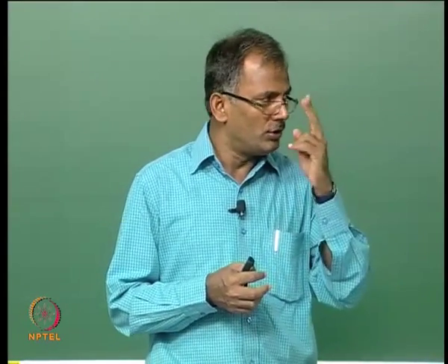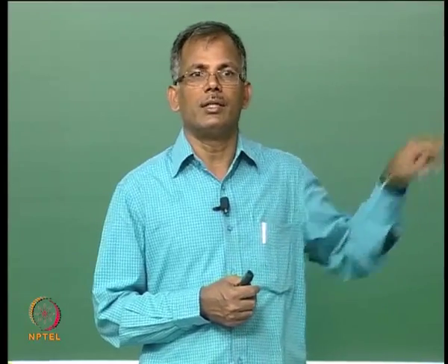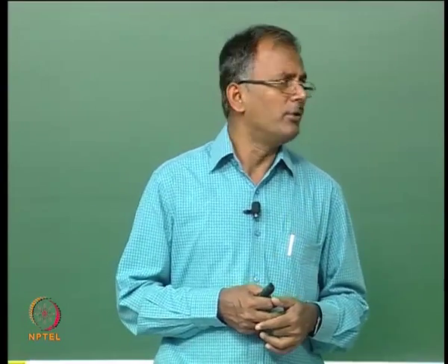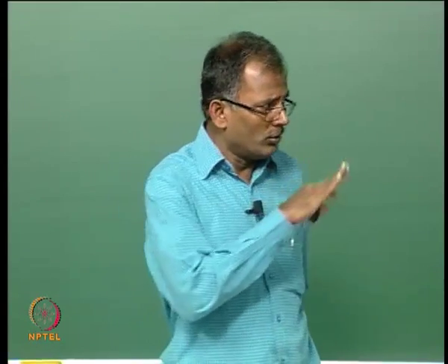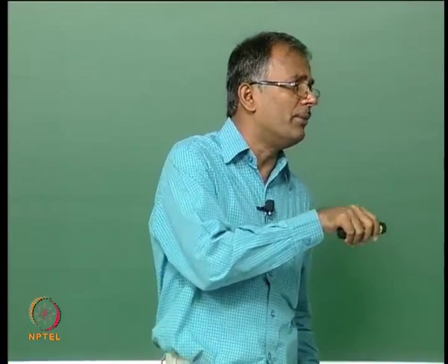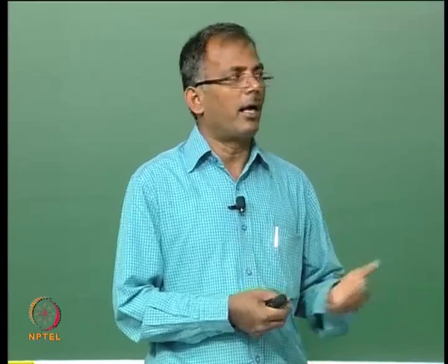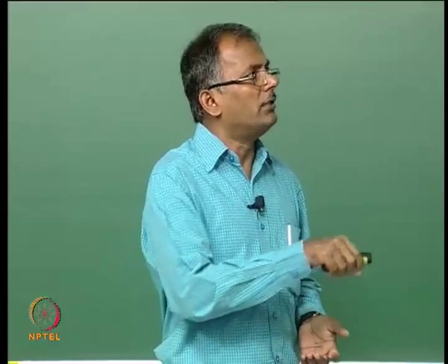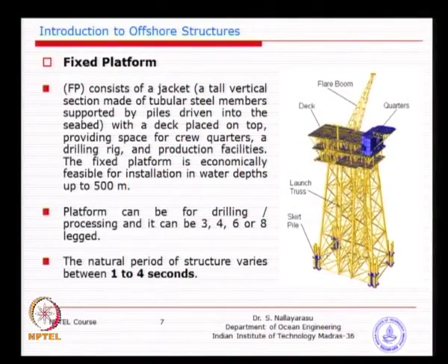So, once you know these two subjects, then you can speak more. But let us not go into that right now, because you will be doing this dynamics course in this semester, I think, or next semester. Once you get into the dynamics of the system, then you will realize the importance of this number. But historically it is proven that most of the structures have the period, because it is bottom fixed and has a pile foundation to the ground, and it is a frame structure. You will find that most of the vibrating period is less than 4 seconds.